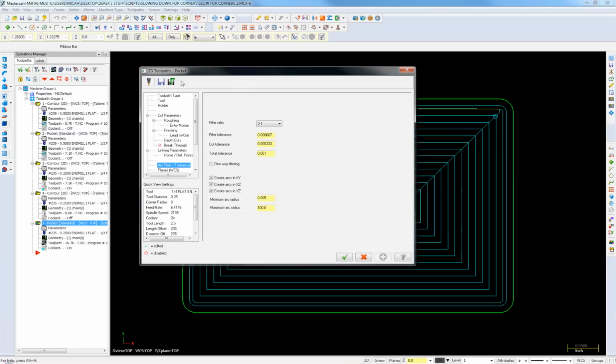One thing to really watch out for, which is definitely somewhat related, is that if you're just doing 2D milling and you have splines or dirty 2D geometry of some sort where there's a lot of small moves, this will always help. But either way, you need to be real careful with cutter comp, because there's going to be certain situations where the arcs are so small, the moves are so small, regardless of whether it's filtered or not, you would not want to use cutter comp, or you'd have to do some extra work on the filtering and geometry cleanup. Okay, so that's something to watch for.